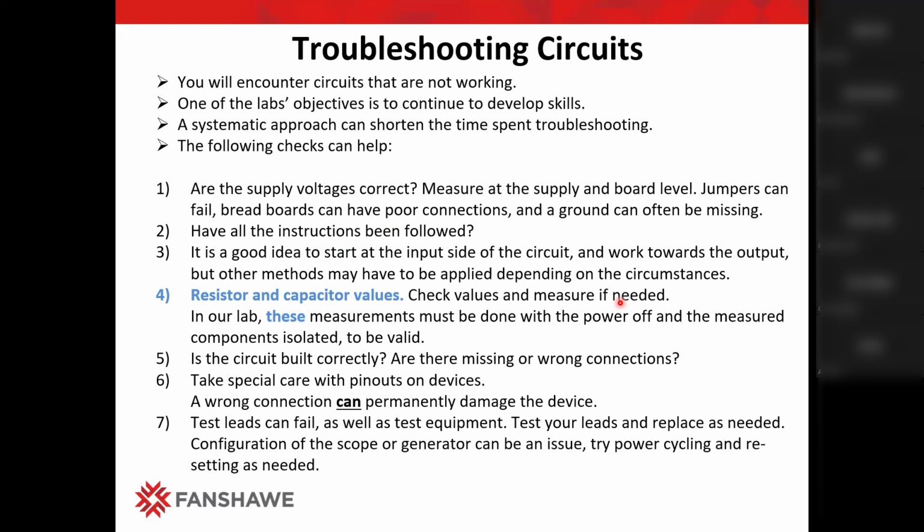Quite often, when I was working a long time ago repairing musical instruments, keyboards, mixing boards, amplifiers, and whatnot, whenever I saw some of those diodes around op amps and other circuitry in that troubled area, I would just take them out and replace them, because those diodes are funny. Sometimes even if they check okay with the meter, still something is wrong with them.